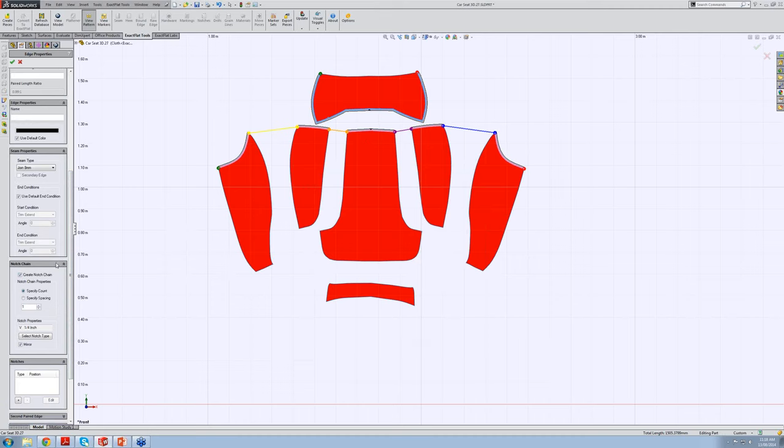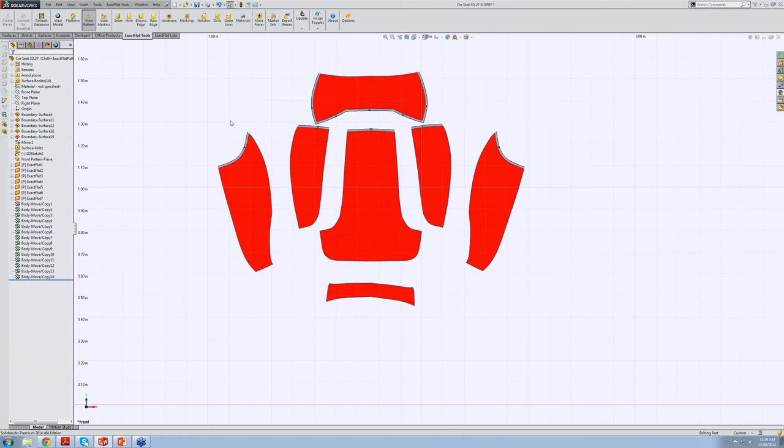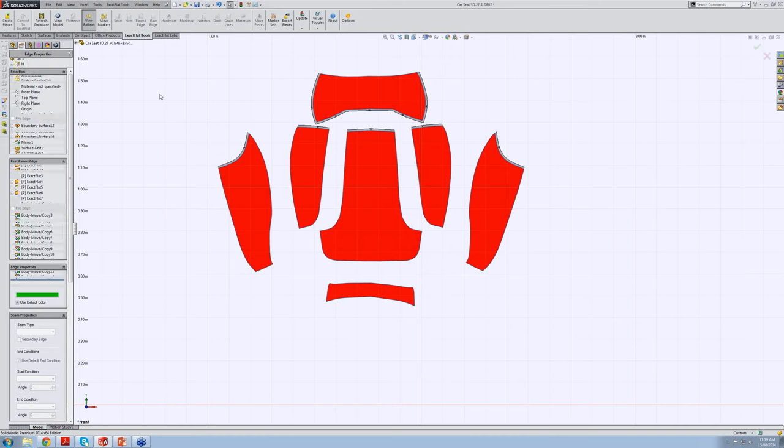So Keith put an 8mm join on here, and now we're going to put some alignment notches on. There's a number of ways we can do alignment notches. We're going to do them in an automated way here. We can either specify by count, or we can specify by spacing between. So we're going to use specify by count right now. And let's just go across this edge and put maybe 5 or 6 notches in. Let's see what happens with 5 or 6 notches. We can also precision place notches manually by picking a point and having it found on the other point. And if anybody wants to see a demonstration of how that's done, we'd be happy to do so.